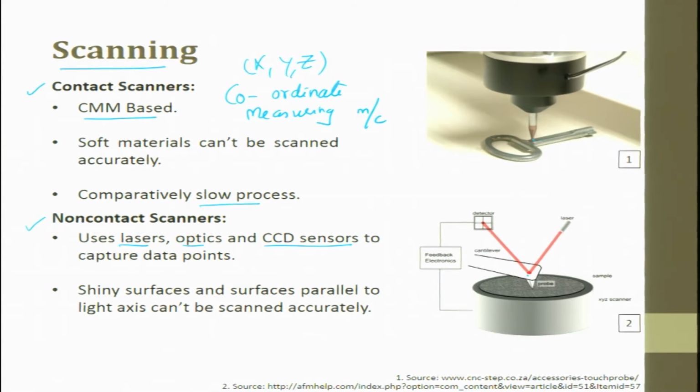The laser hits the back side of the probe. The moment the probe moves up and down, the laser also moves up and down, and this is detected by a photodiode. The photodiode moves in left and right direction and gives you a voltage. Now the feedback electronics is used to convert the voltage into linear displacement, and you get the output.